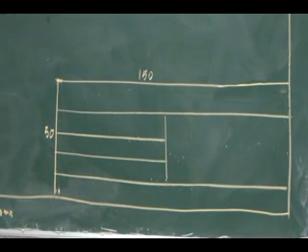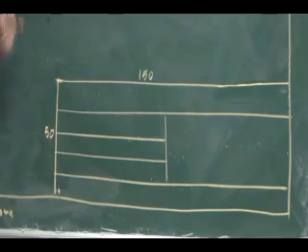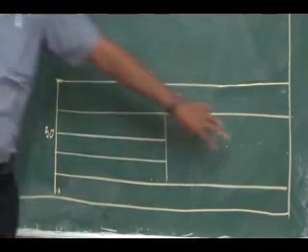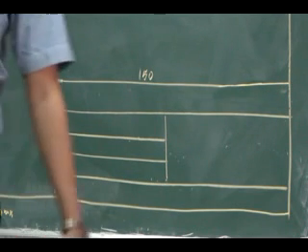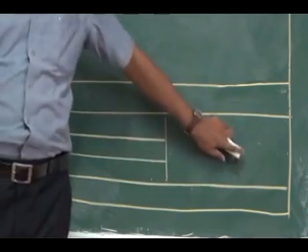So all are 10 mm. The box heights are 10 mm. Even though it looks like some deviation, it is 10 mm height. This is the portion, a big gap you have, where you are going to show the symbol of the projection, in which angle projection you have used. You will be showing that in this box.